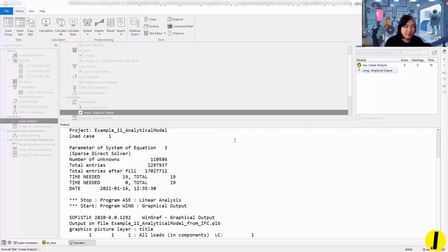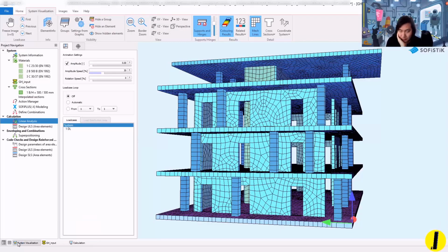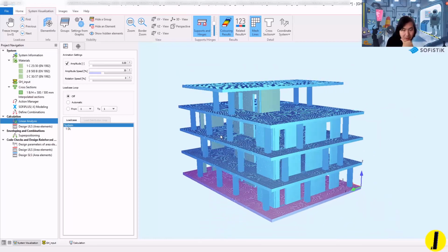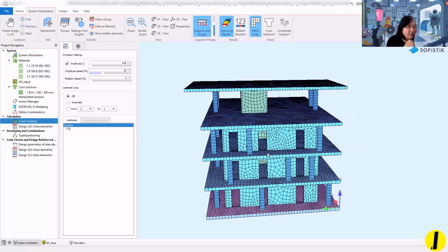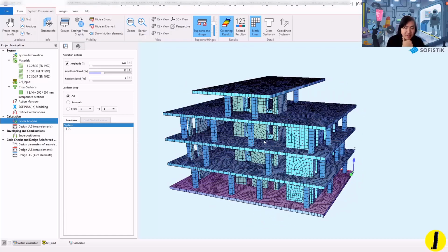I'm gonna have to find out how we can remove this duplicated project parameter. Generally, obviously we can just delete, but maybe we have to filter a project parameter name that doesn't have any value. We find out from the string, and that could be interesting topic. I'm gonna research about it, and maybe with RhinoInside we can filter all project parameter which doesn't have value that we can delete from the system. Then previously with the phase option, we could use this IFC link in the same model.